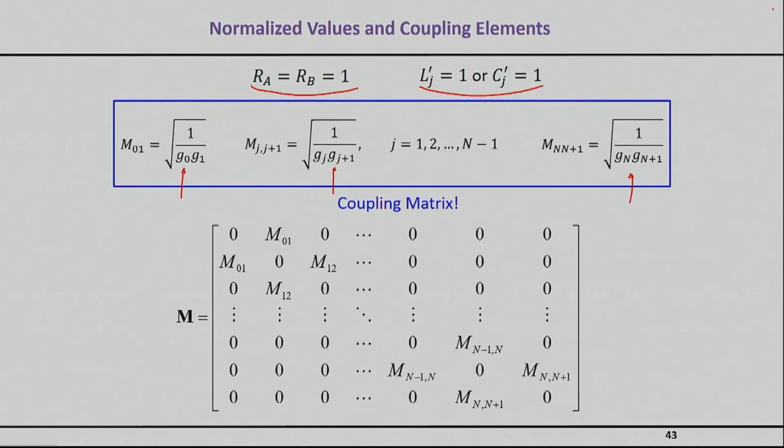Now, exactly the same thing applies for K, and for this type of normalization, we use this common name M to essentially indicate the values of the coupling sections. And in fact, now that we have all of these coupling sections, we can basically put them in a matrix form, and we have suddenly arrived at our very first, the simplest possible way of visualizing our coupling matrix.